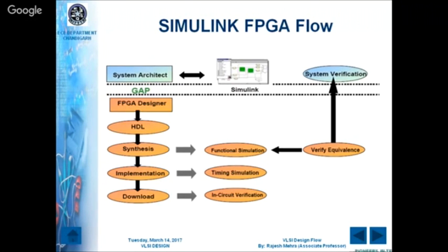Again, whether you are using System Generator or AccelDSP, once your VHDL or Verilog code is available with you, the next step is again what? You have to synthesize, you have to check the resources, you have to check the behavioral simulation, you have to check the speed of your design, and once synthesis is done, then you have to implement the design. Implementation of the design again contains those three parts: translation, placement, routing.